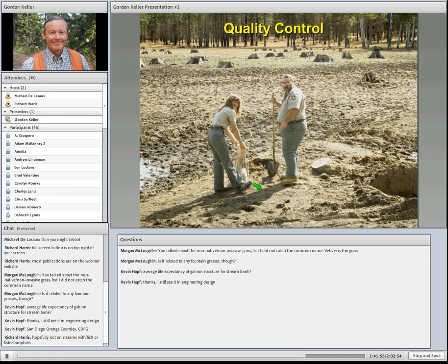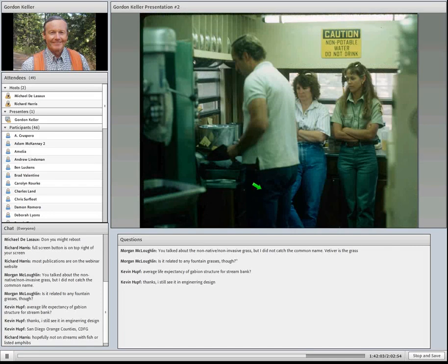So the sampling part of it out in the field is, and then you spend some money if you're doing lab testing, so you want to make sure you've got what you're going to be using. You may run it through a series of lab tests, for gradation, for plasticity index, for LA Rattler, just a whole variety of tests for quality control. You may want to need it for a Proctor or a compaction curve. So there's a lot of things you have to do in a lab to actually determine those properties. There are some nice field methods that have been developed for estimates, but if you're on a big project, you'll probably do it as the testing in the laboratory.